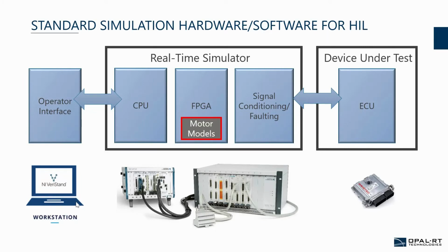Let's go ahead and get ourselves oriented. I've gone ahead and diagrammed a simplified HIL solution. On the right-hand side, we have our device under test. This would be something like your car's ECU, or an inverter controller, or even a wind turbine controller. It connects to the real-time simulator, typically through some signal conditioning and fault interface.